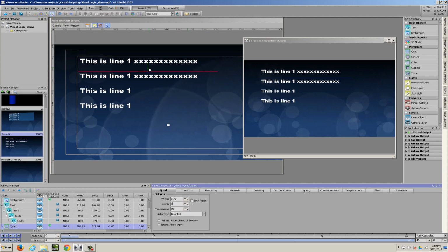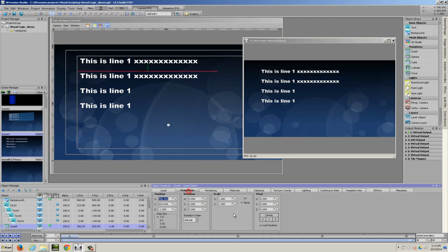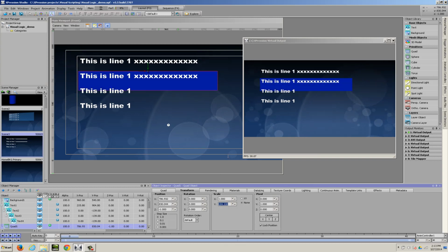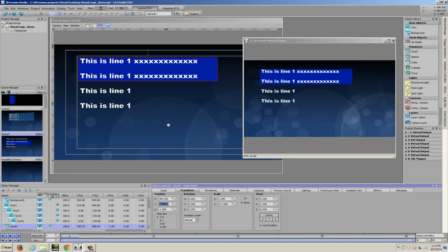We're also going to position the pivot point at +1 so that when I increase the scale, my object scales vertically in a downward direction. Because obviously my text objects, as I insert line breaks, are scaling in a descending fashion, and I want the quad to do the same thing. So we just want to make that one modification so that it scales from its top edge effectively.